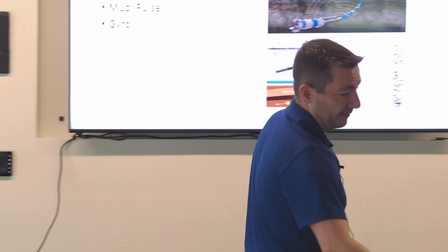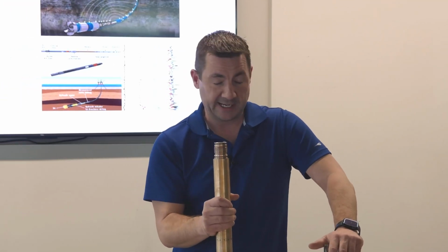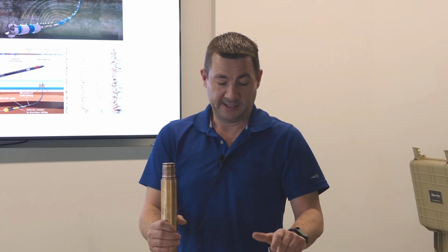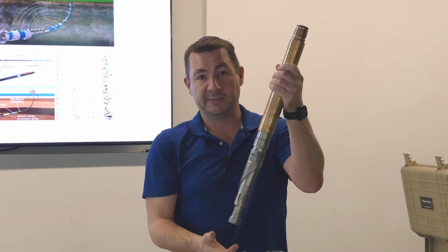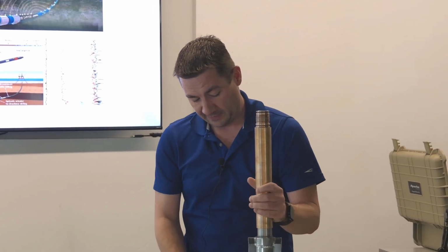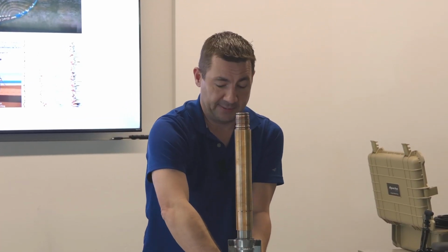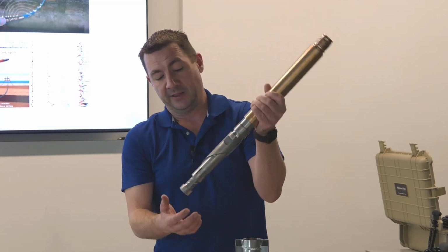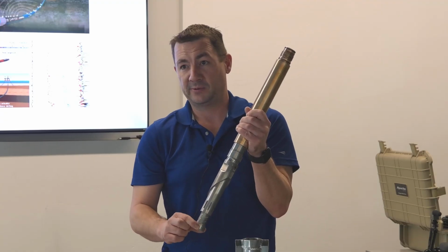This is the bottom part of the tool. The mud pulse tool sits inside of this sleeve, kind of like the gap sub, as I was explaining before. Instead of transmitting out of the gap sub itself, this sits inside of a UBHO, it's called, that the tool will sit down inside. So the signal is transmitted up through the mud column itself. All the mud from the column goes down through here and then down through the top of this mule shoe, as it's called. And then the electronics from the tool will take this and move it up and down, and this creates your sine wave.